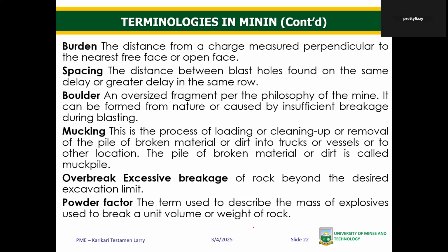Let's look at some of the factors that cause boulders because it's a very serious issue. Now, the burden to spacing ratio. If you increase the burden to spacing ratio, sometimes you get boulders. If you don't put in enough explosives, you get boulders. If there are leakages, it means that you find cracks, so the explosives go into the cracks in the rock.